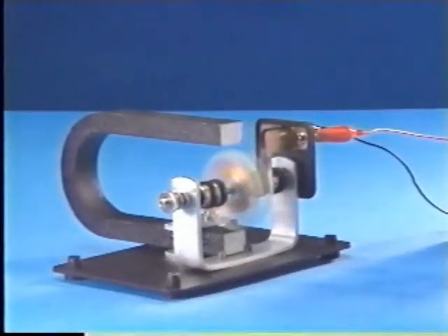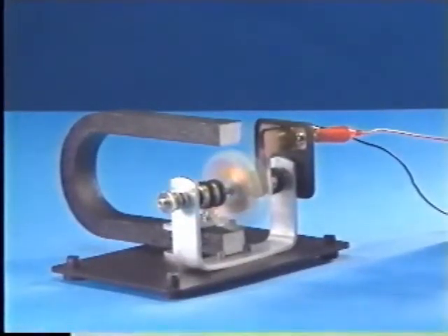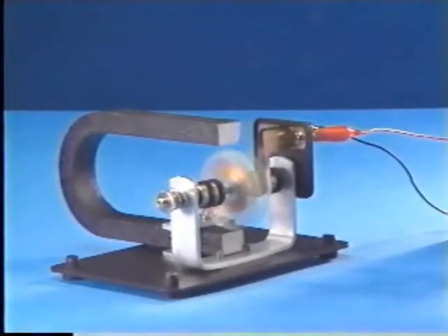This ongoing process, current to the armature, interaction of opposing flux lines, and magnetic push on the armature is what creates movement in an electric motor. Any work that a motor performs is the direct result of this process. As you can see, the relationship between magnetism and electricity is important for both the generation and utilization of AC electricity. Let's stop here and review what you've been shown.